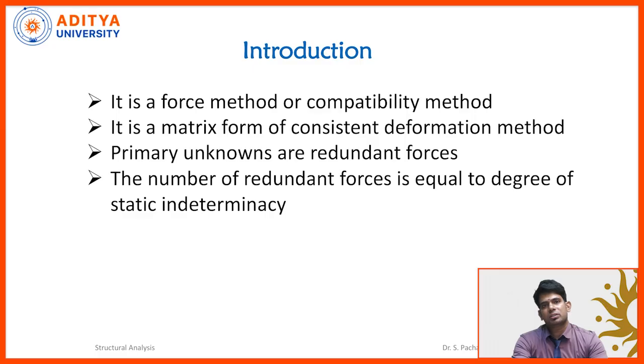So already we discussed enough about the stiffness matrix method and the flexibility matrix method. It's a simple introduction, and then we are going to move towards the numerical problems. You know that the flexibility matrix method is a force based method. It is also called a compatibility method. So it is the matrix form of the consistent deformation method. We all studied the consistent deformation method in structural analysis too. Another name for the consistent deformation method in matrix form is nothing but the flexibility matrix method.